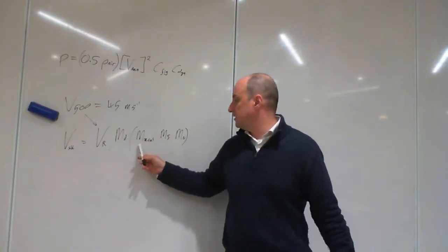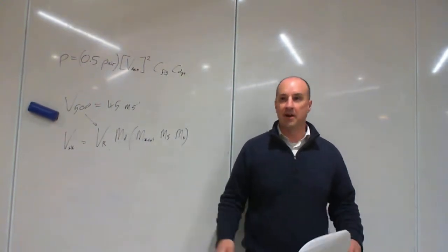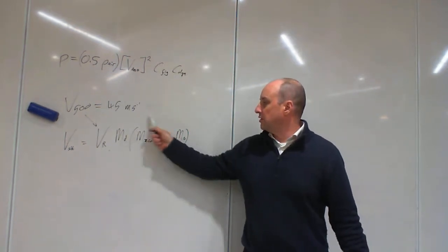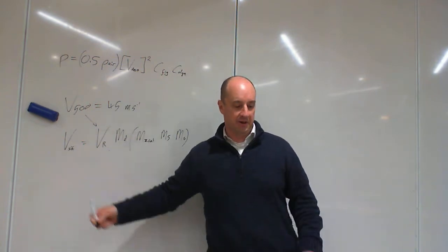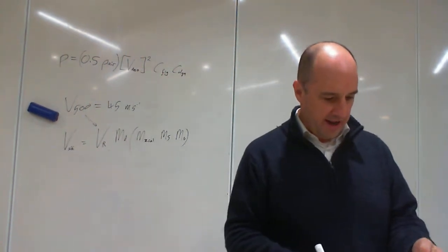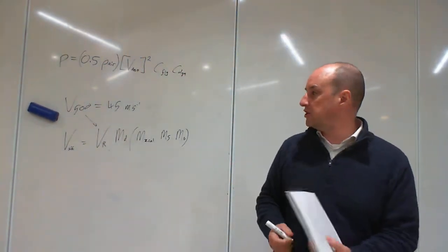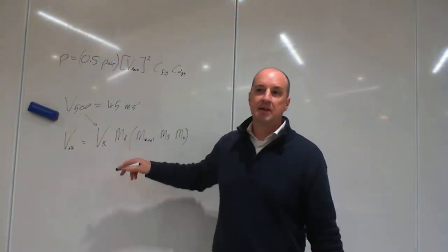And these ones are just modification factors. All right, and we'll work through what each of those are. We multiply them out, and we're going to get our V, which is our wind speed for the site, for the direction. So the first one is the direction multiplier. MD is a direction multiplier.